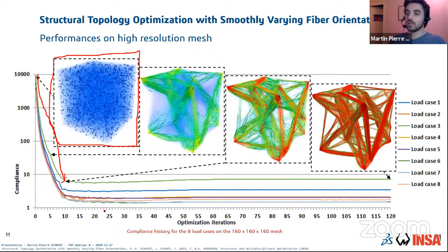After these iterations, we can see that there are some oscillations in the compliances for the 8 load cases. This is due to the simulated annealing part of the update scheme that is basically shaking things up so that the fiber orientations settle in the best local minimum that they can find. And in most cases, using this approach, after 40 to 60 iterations the design converges, with all the design variable fields staying fairly stable.